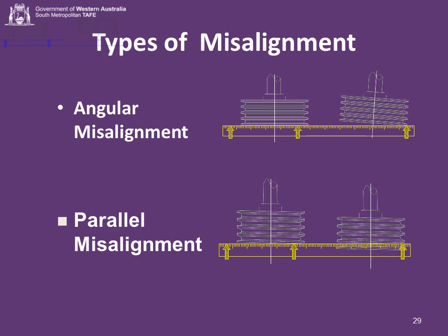Basically, any degree of misalignment, angular or parallel, will decrease the normal service life of a belt. Angular misalignment results in accelerated belt and sheave wear and potential belt stability problems with individual V-belts. A related problem, uneven belt or cord loading, results in unequal load sharing within multiple belt drives and can lead to premature failure. Symptoms such as high belt tracking forces, uneven tooth-land wear, edge wear, high noise, and tensile failure are indicators of misalignment.